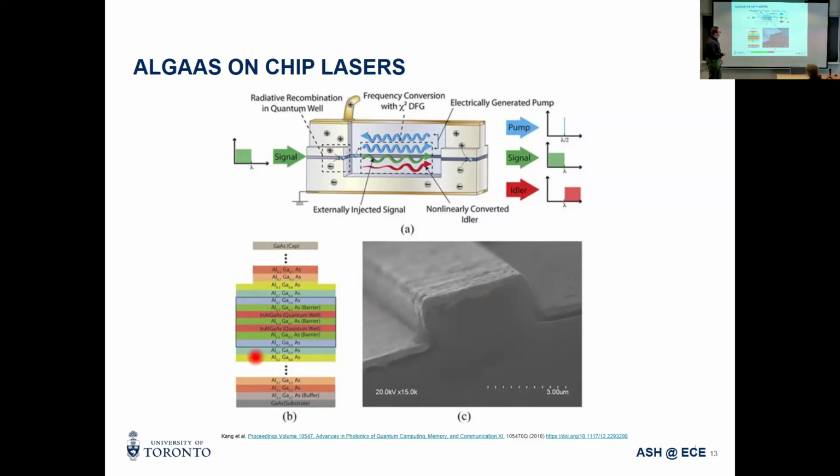And then in the middle, for the core of our waveguide, we have 2 quantum wells surrounded by 3 quantum barriers with different doping concentrations of aluminum gallium arsenide. What we can do with this is create a P contact and an N contact and launch a potential difference within the quantum wells so that we can actually get lasing out of this. And then an SEM of this structure is shown here.